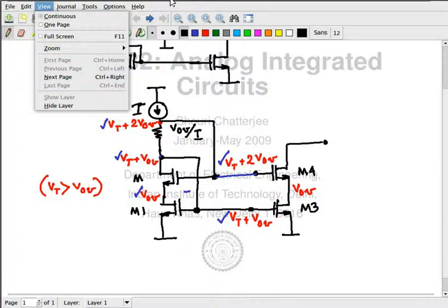Usually we don't build temperature invariant current sources. We do build temperature invariant voltage sources. But with temperature, we would like the current to adjust itself so that the MOSFETs still behave the way we want them to behave. Okay? So that reference current source is not really a reference. It's a current source. It's not of exactly precisely the value we want.